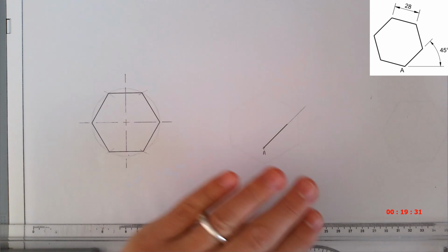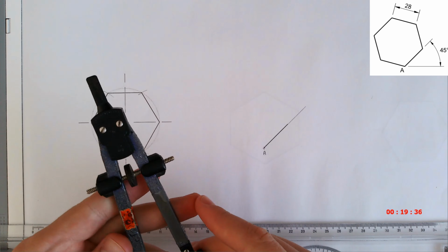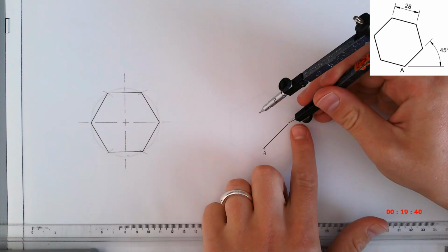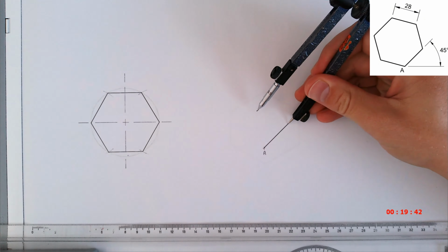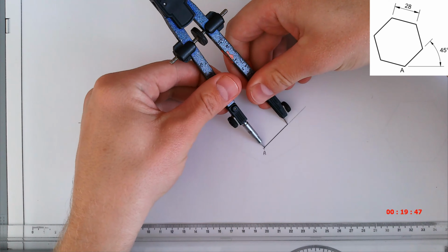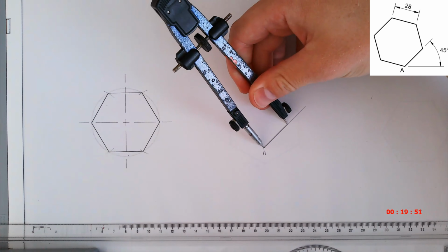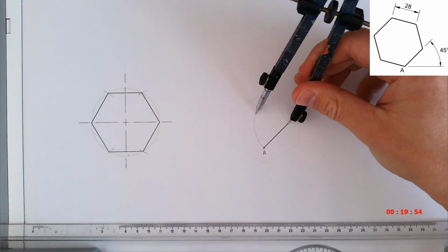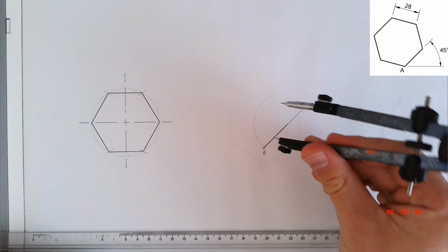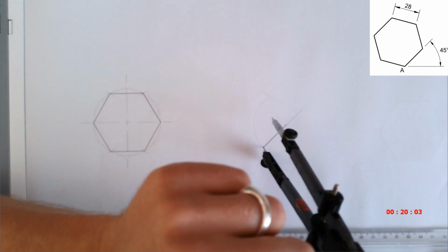And now for this method, when they give it to you in this format, we are going to use our compass. So I'm going to put my sharp point on the one end of the line, the lead there to the starting position, which was A. Then I am going to draw a light arc like so. Now I'm taking my compass, I'm putting the sharp point on this part of the line, the starting position.